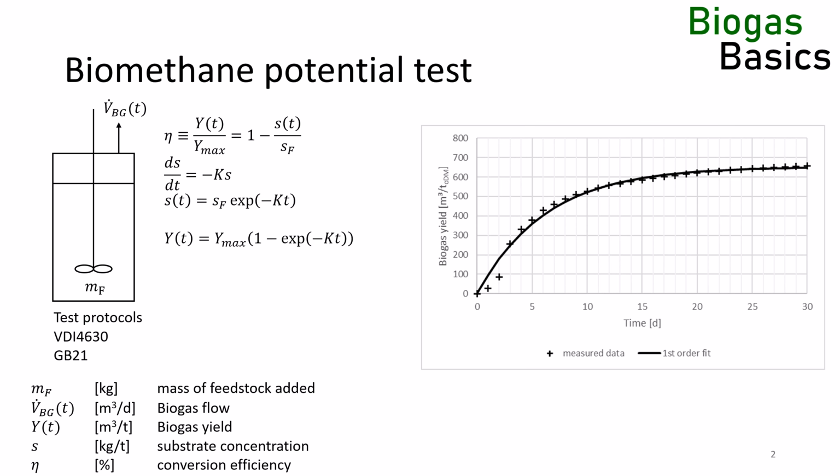The reason for the poor fit at the beginning of the experiment is the so-called lag phase. During the lag phase, the microorganisms adapt to the new environment and do not grow. Lag phases often have random lengths, and more importantly, they are a function of the respective cultivation and not a feedstock or even a biological parameter. For a scale-up, especially for a scale-up into a continuous culture, the lag phase does not matter. Thus, we can shift the gas production curve by correcting the time with the lag phase, fit the BMP curve, and then discard the lag phase.